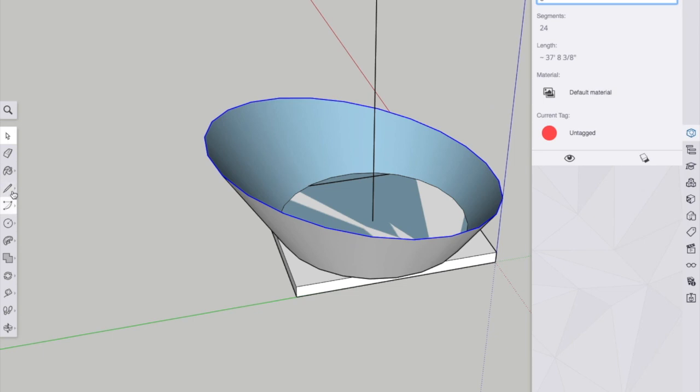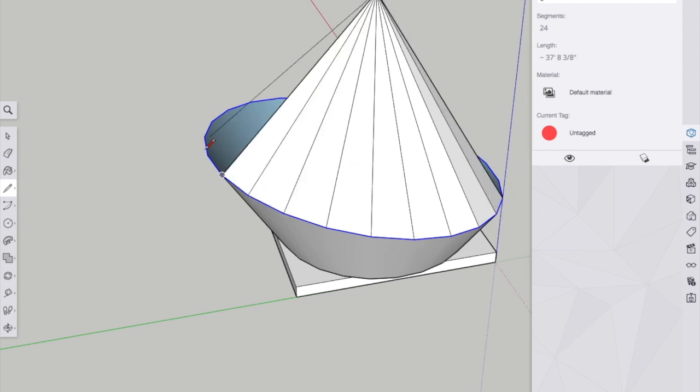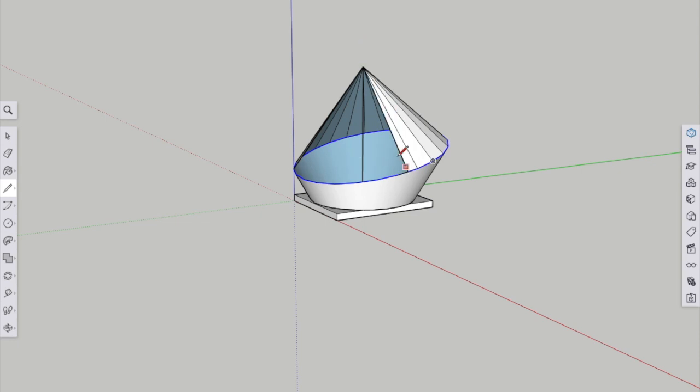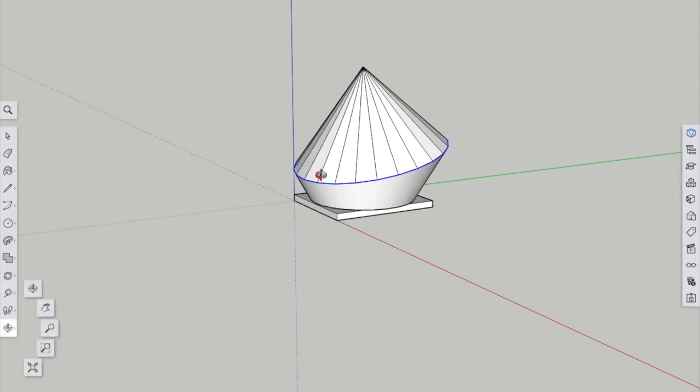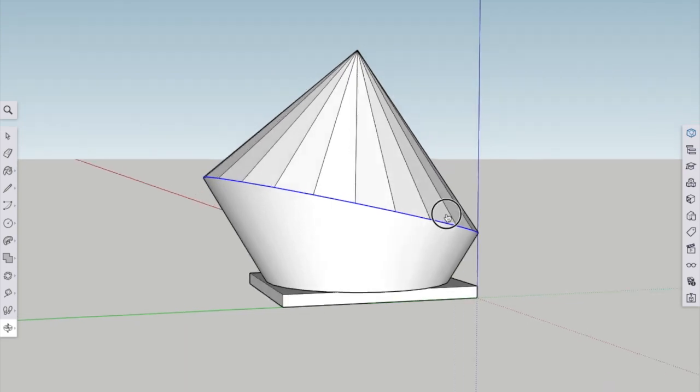Alright, so now I'm filling in the top, and this is just sketching to show you what it looks like proportion-wise. This is not the structure of this thing at all, but anyway, I'm just drawing lines, and SketchUp automatically fills in that face once I've enclosed an area. So you can see I've just drawn a line and it encloses it. So here it is, a finished sketch.